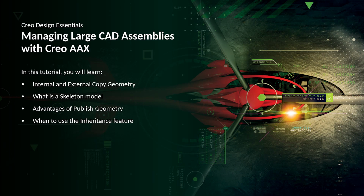So here we come to publish geometry. Usually in the skeleton model, you are going to design all the top level information, a lot of references, a lot of surfaces, a lot of curves. So you know which curve or which surface you want to share with which engineer or which model. The method to share this, we use publish geometry.